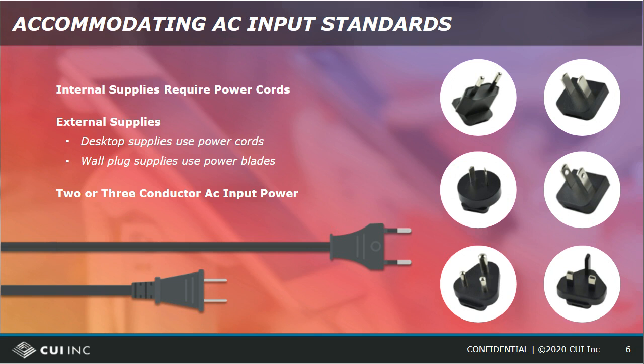One other choice you have to worry about with AC power is whether you want a 3 or a 2 conductor input cord. And again, if you recall earlier, we're talking down at a few hundred watts. So this is single phase AC design, and we won't discuss multi-phase AC design. But with single phase AC design, power is conducted over 2 conductors. If the third conductor is present, it's therefore ground, which is a safety feature. Not all products require that ground, and so you have to decide if your product will or will not require the addition of that ground conductor.